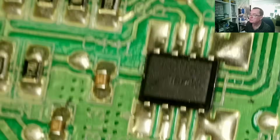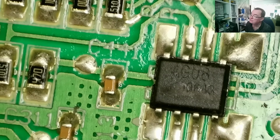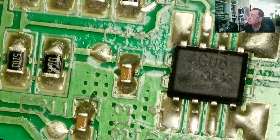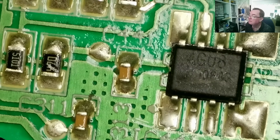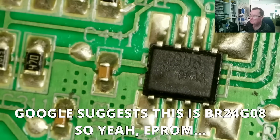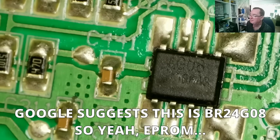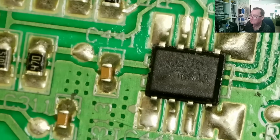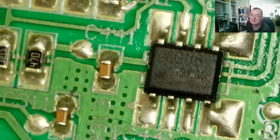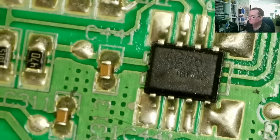So, suspected EEPROM just says 4G08, and I can't quite make out the other number at the moment. Okay. Is it worth finding out? Probably not, because we could take it off the board, put it into an EEPROM programmer and read the contents, write all F's to it, FF, and then write back the original contents and do a verify, and if it passes then the EEPROM is fine.